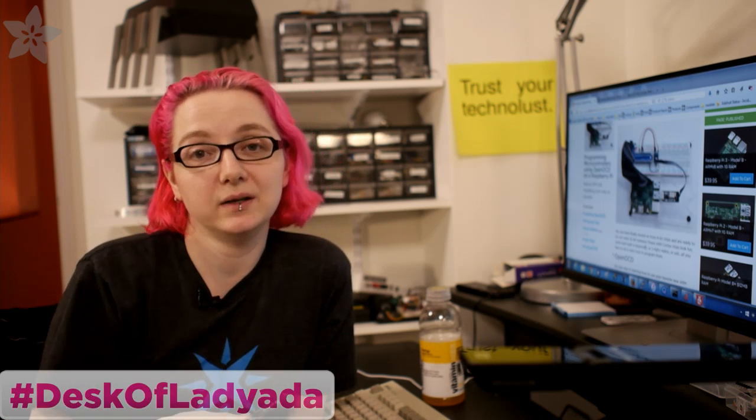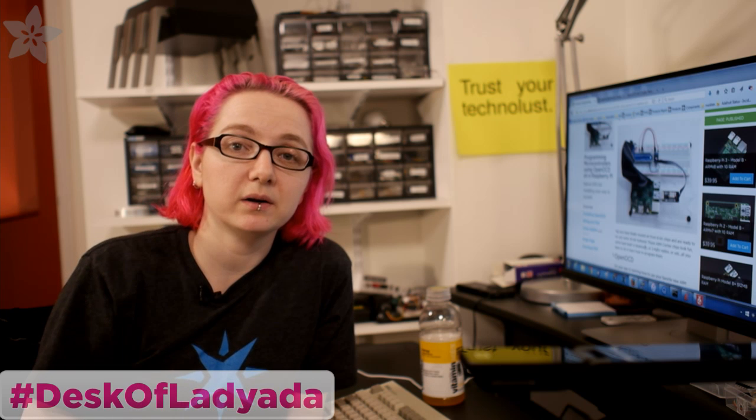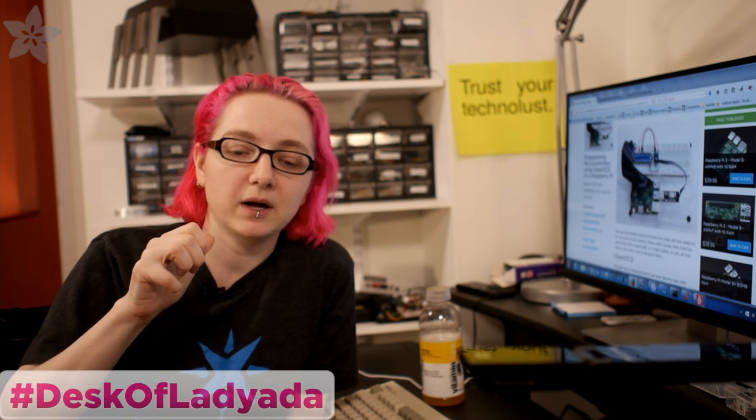However, when you get to chips like that ATSAMD21 or maybe the nRF51822 and other Cortex chips, you can't do that anymore. The protocol required to program these chips is called SWD, I think single wire debug or something. I don't know exactly what it stands for, but it's a debugging and programming protocol. It's a 2-wire protocol, plus ground: clock and data. The clock comes from master to slave, and the data line is actually bidirectional. It's a little bit like 3-wire SPI, if you've ever used that.